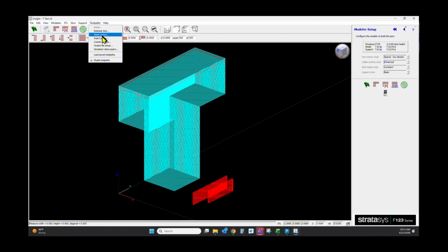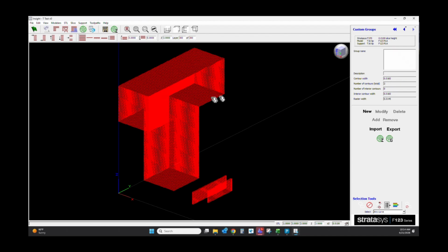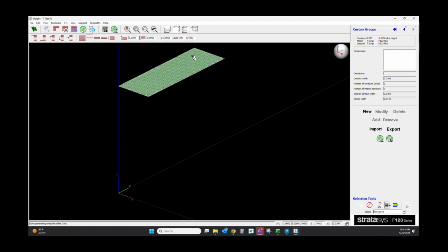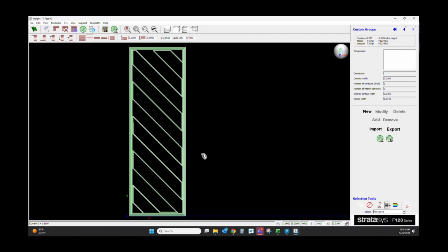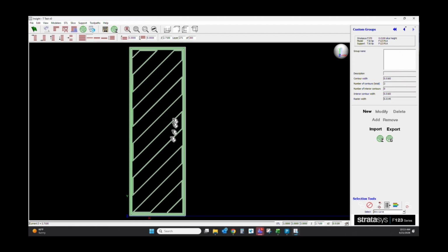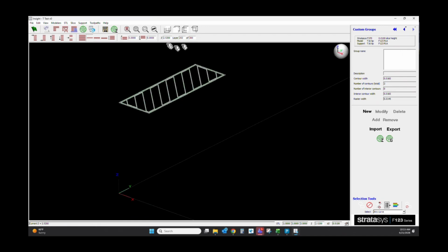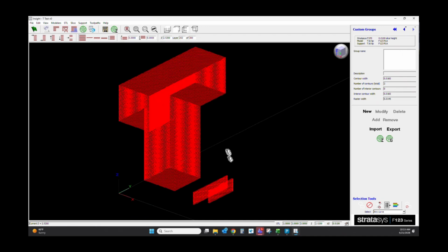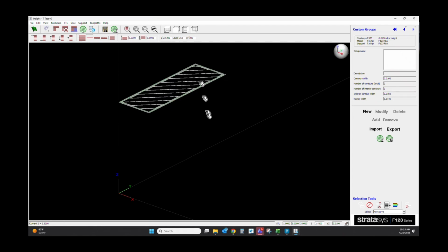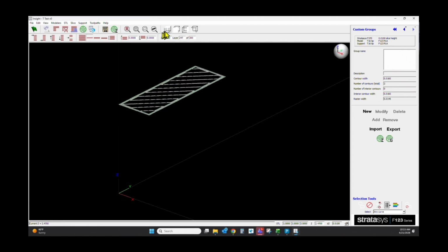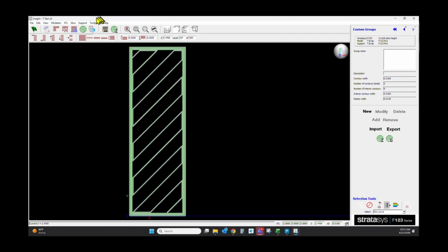So for this exercise, I'll bring that up. And we will create a new group. So PLA always builds super duper sparse. As you can see here, it's got a 200 thousandths spacing on the interior. Maybe you need this to be a little bit more rigid. You're trying to use up some of your PLA that you've got laying around, but you need it to be more rigid than the standard PLA parts that you've processed in the past. So we can use this to override.